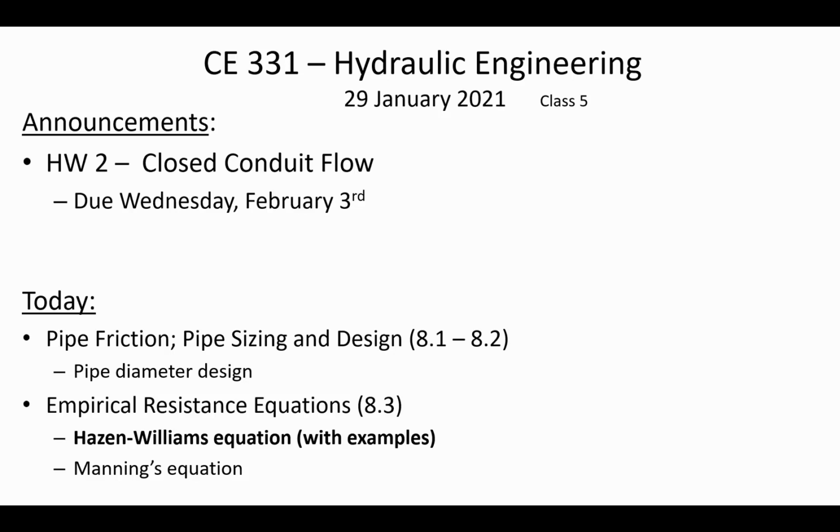Today we're going to begin on section 8 in the book, and continue talking from section 8 because the iterative spreadsheet design that we did on Wednesday was related to those ideas. But we're also going to continue into playing around with some of the other empirical resistance equations besides the Darcy-Weisbach equation. They're not as accurate, but they are simple to use, and so we should get some experience and practice, and you'll most likely encounter them when you take the FE exam. So it's important to know all 3 methods for calculating frictional losses.